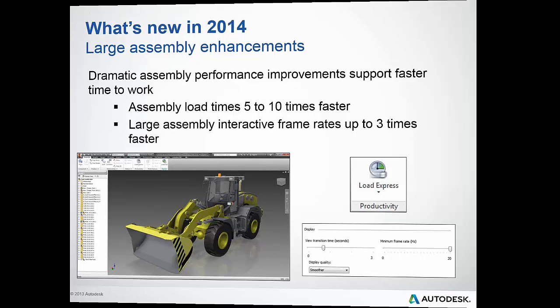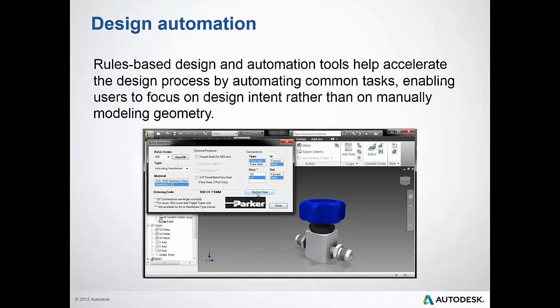Another thing is standard parts. Everybody had libraries, but what you really want to do in your assembly is put the part in that you're purchasing it from. So here's the vendor, Parker, and we're going to purchase this part from Parker. So now when we do a bill of materials, we actually have the right part number that we're going to order. All the specs are there, the weights and everything. So when you do analysis, you don't have to guess at anything.